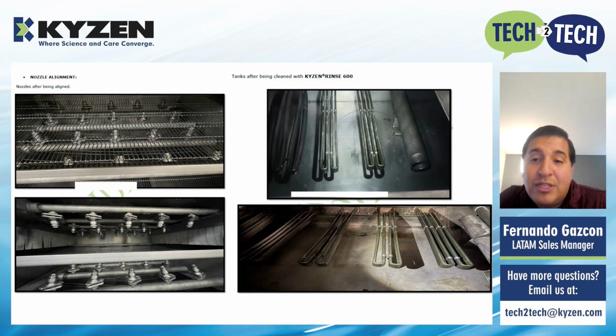We provided the CM with a specialized cleaning chemical named KYZEN Rin 600. This is used to recirculate through the entire equipment for 3 to 4 hours. This helps to dissolve all this scale buildup in the walls of your tanks and also inside the tubings, spray bars and pumps. We recommend a full maintenance cleanup of your equipment like this one at least once per year to ensure your cleaning equipment stays in shape and is optimal.